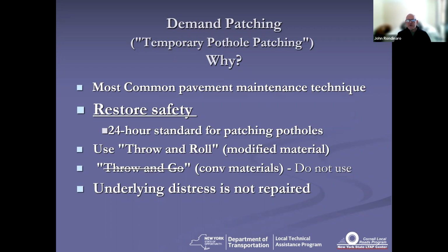In the old days, we used to use a technique called throw and go, and we paired that up with the use of conventional materials. But typically, you'd put the material in the hole, and it'd last for about 10 seconds. So now we focus on the use of the throw and roll technique, and you pair that up with the use of the engineered or modified materials, and you've got a patch that'll last for the season. The one thing you want to remember with any of these temporary or demand patching activities is you're not repairing any of the underlying distress.